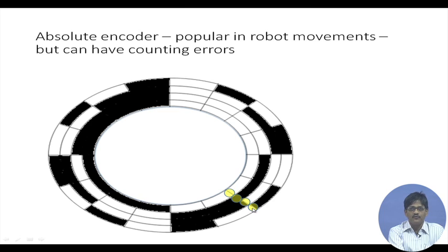While change is taking place in the first channel, say in the second channel there is a slight phase difference, so that the change has not yet taken place, so it might read at this particular position 1, 0, 1, 1, because the first channel has not yet changed.